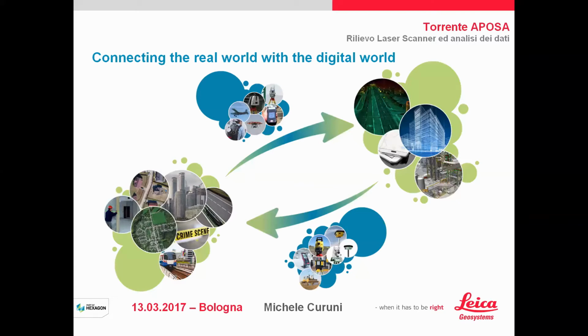the target of the big companies that work today with survey tools, because today every survey tool produces a point cloud. If you think about photogrammetry from drone, or laser scanner mounted on drone, or aerial cameras, terrestrial laser scanner, mobile laser scanner, total station that does scanning, and backpack scanning, every tool can produce a point cloud. And this is very important because the point cloud today is a digital copy